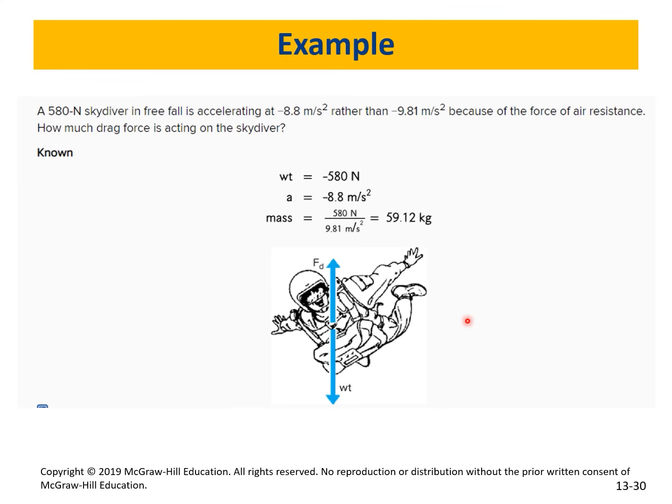So now how much drag force is generated to keep them in that position? And we're calling it drag because it's aerodynamics. And we're going to come to that later on in another chapter. Do you know how we got the mass? You have the 580 newtons, that's the weight. F equals m times acceleration, so you divide by 9.81, and it will give you how much mass the subject is in kilograms, because we needed to multiply it with the acceleration. Do we have a number? 0.7? Okay, so here's what we're going to do.